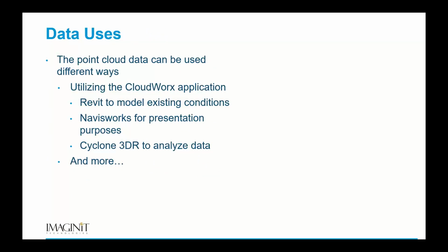Looking at this, I kind of touched on it just now, but now that we've got all this data, what do we use it for? Oh man, where could we not use it? Let's see. Take it into Autodesk applications using CloudWorks. If I use CloudWorks for AutoCAD, I can cut sections and view different views. I can do surfaces. I can do points on grid for your civil, your COGO points. I can create 2D floor plans by slicing the point cloud and using the floor plan tool to click on the points. These are walls, and it puts them in for me.